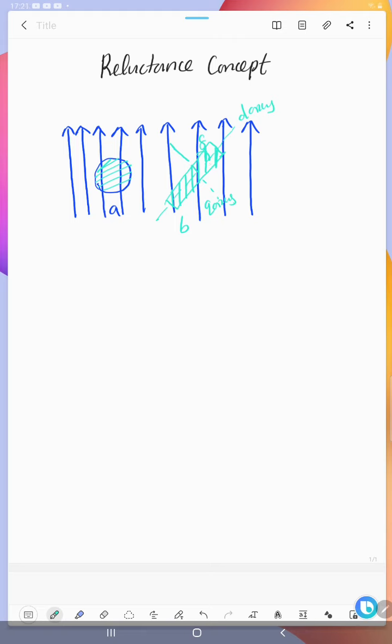The D axis of the object B does not coincide with the lines of the magnetic field. The object will introduce distortions into the magnetic field. In this case, the direction of the distorted magnetic lines will coincide with the Q axis of the object.